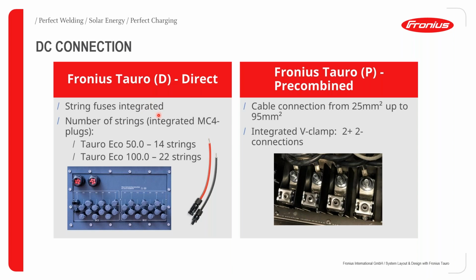What is the advantage of having your string fuses integrated in your inverter? There's no need to have string fuses in a DC combiner box or a DC protection box, because you have fuses integrated in the inverter.